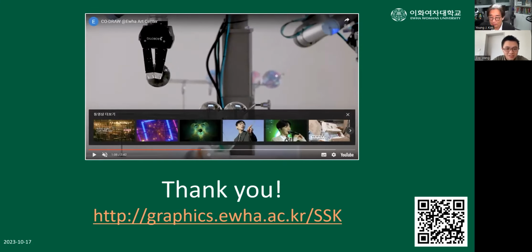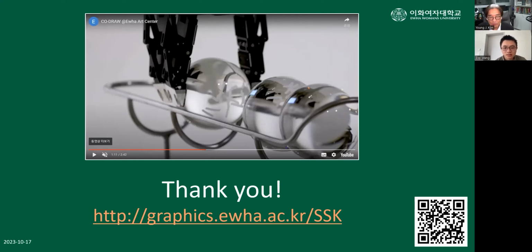Yeah, we didn't use force sensors or torque sensors to control the width of the drawing. We didn't do it, even though we can. The main reason is that we are using a pen, so the final drawing width is always fixed. No matter how you push it, if you push really hard, the pen will be broken. So the width is almost hard to control. You may draw a really thin line if you slightly touch it, but that is hardly visible. If you push with enough force, it starts to draw a kind of fixed width. So for pen drawing, controlling the width is almost not practical. But if you use other mediums, then definitely you can use force control to control the width of strokes.